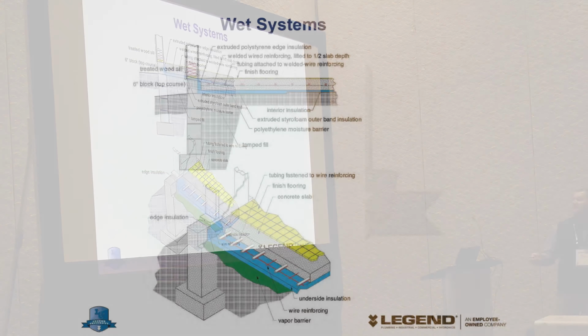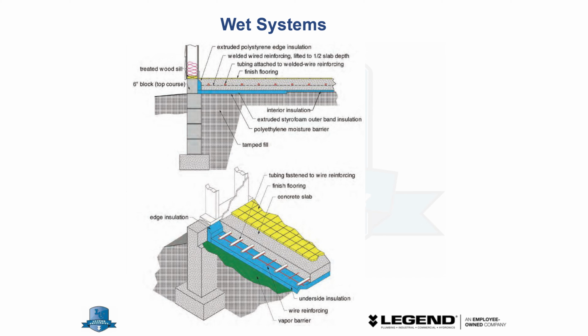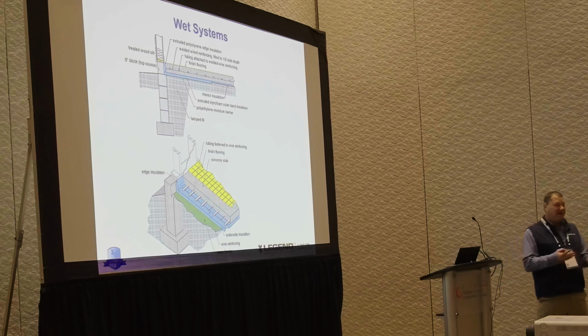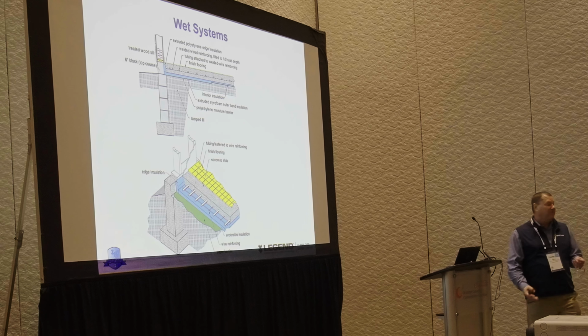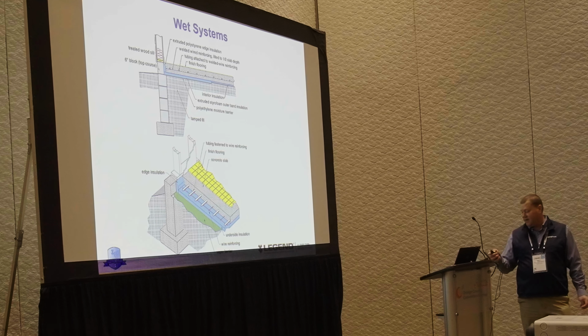And this is probably one of the biggest issues: you need to put insulation underneath here. In some municipalities, there's no radiant code. There are a few states that have adopted the radiant code. What the radiant code says is the minimum is an R10, a 2-inch foam. That's best practice. That's what they want. That's going to be an R10 below. So when we put our resistance above it, we want to be significantly less than that. It'll force the heat up, and we want to have that thermal break.